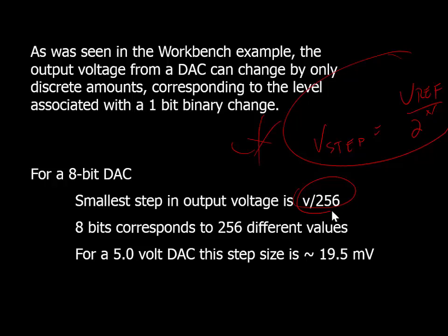And you need to know it so importantly that you should make sure you know it before you take your final exam, because there will probably be at least one question where you'll be asked, what is the step voltage for a 12-bit A to D with V reference? For example, V reference might be 3 volts, and N is 12. What is our step voltage? You just plug those numbers in.